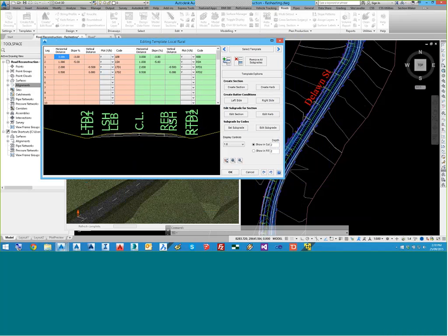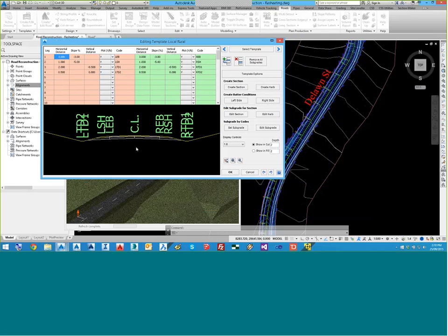Another thing I wanted to show you today was a method of controlling table drains and adding them and inserting them dependent on cut and fill. But I didn't want to use the table drains command in the design data form because that can be limiting. These table drains that I've added are driven by a string that I've created. So I'll show you that a little bit later on.